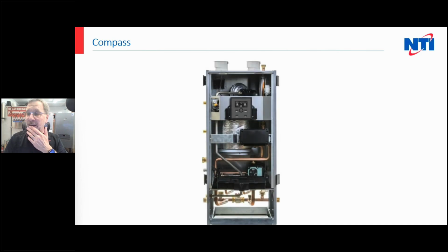Now let's rotate this thing around a little bit. Oh, let's first flip the door down. So that's how open it is inside. You'll notice that the high voltage box, which is right here, is a little bit more beefed up than what you're used to on an FTVN. You see on the control, we've given you a bigger bracket and allowed you access to the gas valve. But if you need to replace that gas valve, you're going to take 4 screws off and just lay that to the side. Just swing it over and put 1 screw on it to hold it in place so it just sits there and you can do anything you want inside.